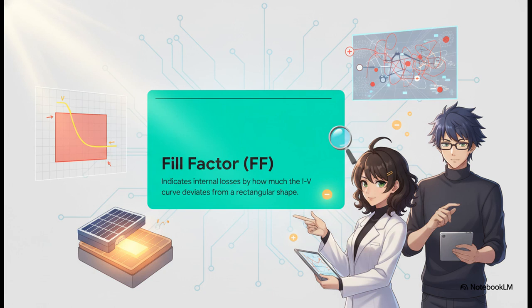Now, while we've got this curve in front of us, we really have to talk about fill factor. Imagine a perfectly, flawlessly ideal solar cell. Its curve wouldn't be curved at all. It would form a sharp, right-angled rectangle. But real-world physics intervenes. The fill factor is a critical metric that reveals the internal health of the cell. It's essentially a visual indication of internal losses, like series and shunt resistance. Basically, the more the curve sags and deviates from that perfect rectangle, the lower the fill factor, and ultimately, the lower the overall efficiency of our device.